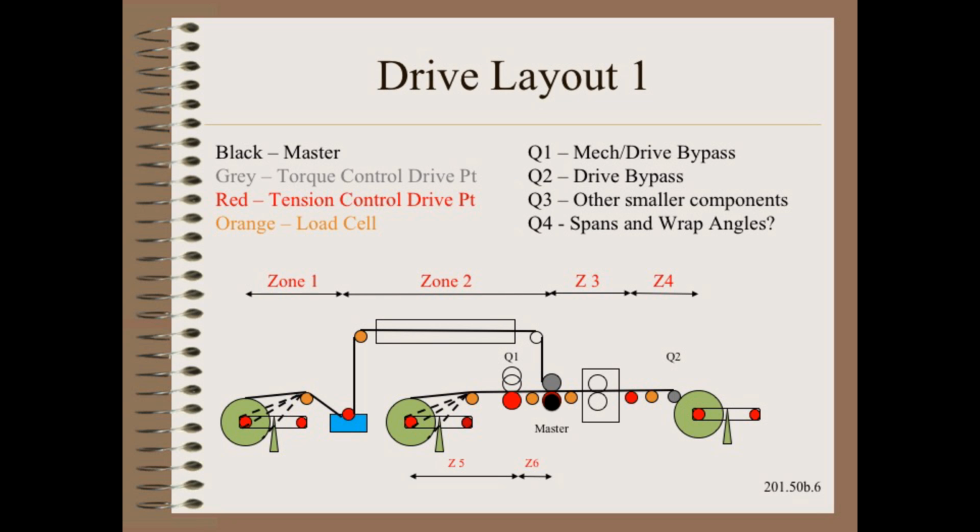It is no trivial matter to do a good center surface wind drive that does not degrade nip control, as we discussed in our 2-day winding class. It is even harder to make the controls for dual drive laminators and the center surface wind drive understandable to the plant process engineers, much less the operator, who will be expected to run the machine on a day-to-day basis. The subject of HMI, or Human-Machine Interface Design, will be the topic of an upcoming clip series. Stay tuned.